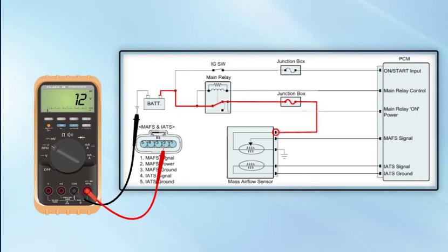If the terminals are difficult to access, you may need to use adapters or back probe the connectors to make voltage measurements. Be sure not to damage the connectors.